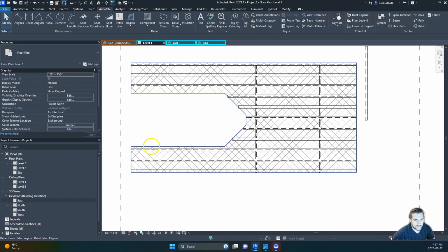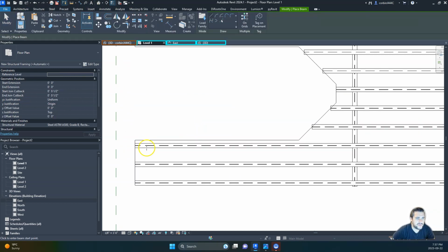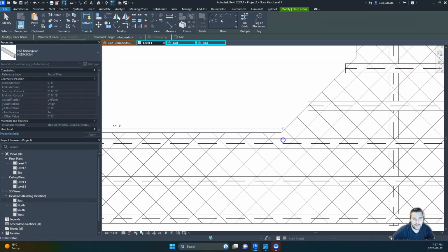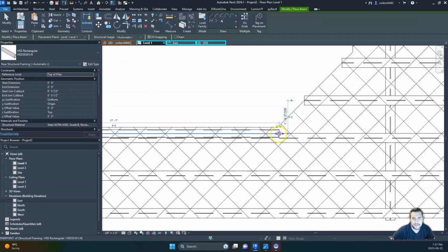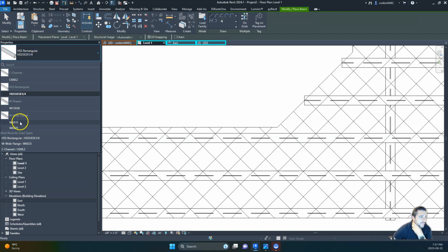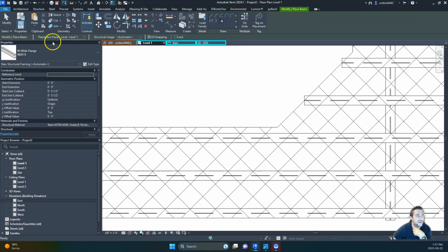So that's our dock there. So now if we go to our structural steel, if these members aren't right on the edge, we might need to physically model that. And what I often do, just for simplicity's sake, is I'll grab a beam, and instead of modeling like we just did, I'll use the pick line, and I'll offset that by 3 inches. Let me see here. We could go to Y offset value and make that 3 inches.